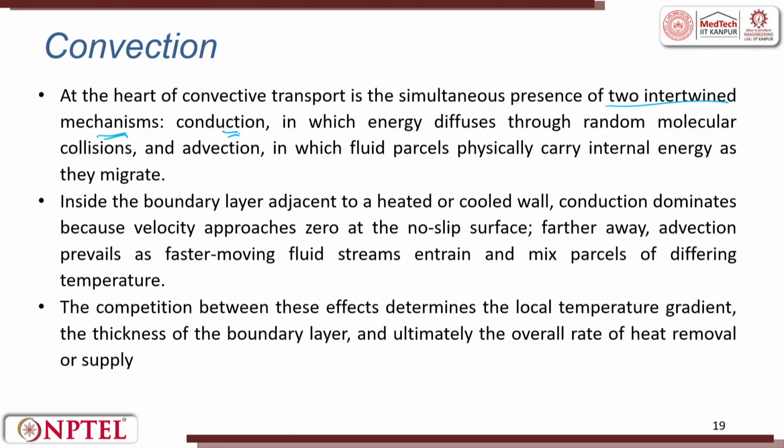One is conduction, in which energy diffuses through random molecular collisions, and the other is advection, in which the fluid parcels physically carry internal energy as they migrate. So, at the heart of convective transport are these two intertwined mechanisms, conduction and advection.